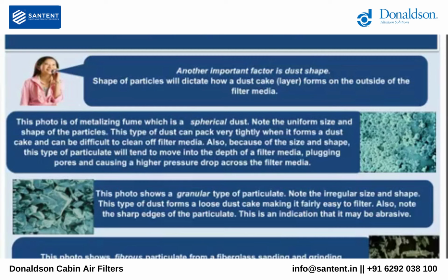This photo shows fibrous particulate from a fiberglass sanding and grinding operation. Note the splintered look of the dust. This causes the material to hold together or be agglomerative. With fibrous dust, extra care needs to be taken in the collector design to keep the dust from bridging over the outlet and in between the filters.